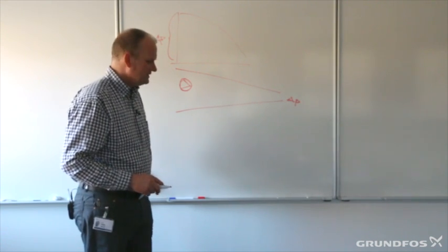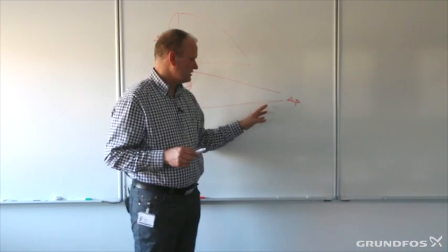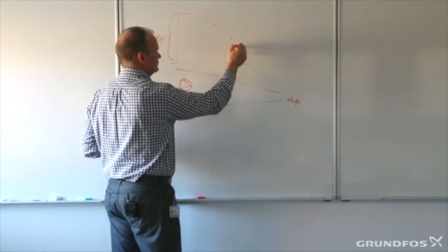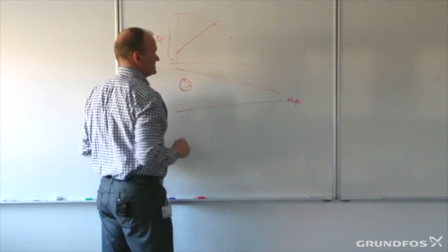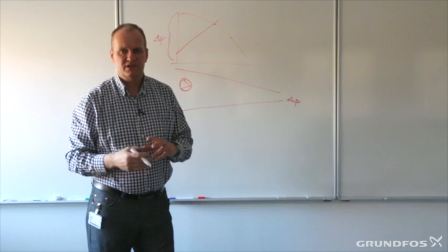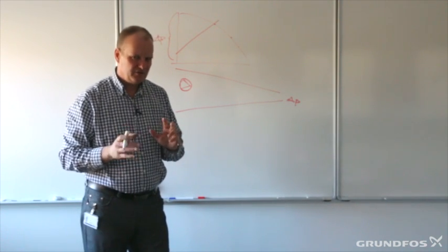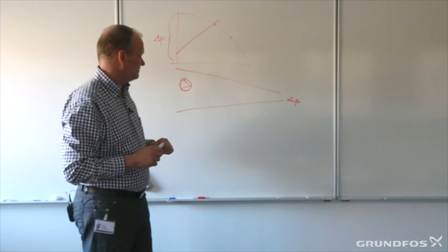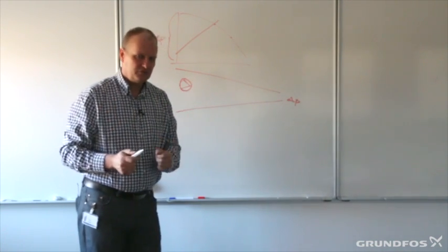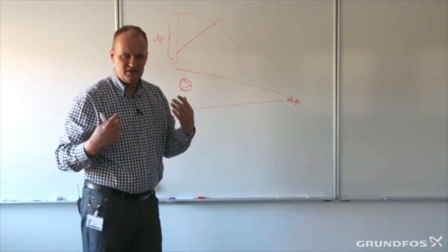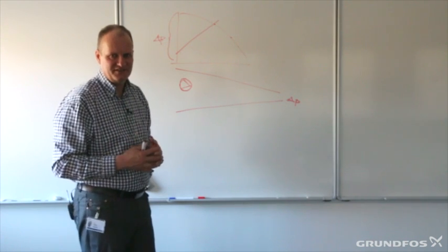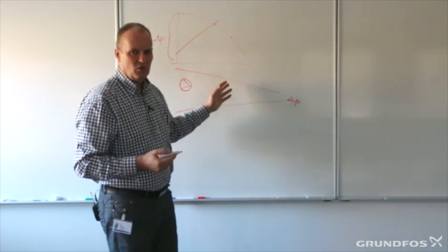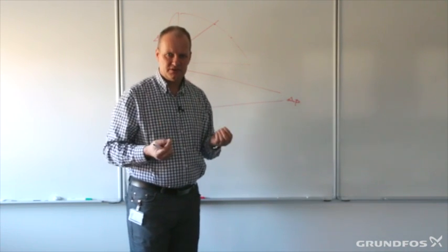And this is about the level of how much differential pressure we should set the pump to operate by when we, for instance, have a magnet pump with proportional pressure, etc. It can be quite hard to determine how much pressure the system actually needs. But what we could do, if we can persuade the consultant engineers or whoever is taking these kinds of decisions, is ask the designer, where do we have our critical point in the system?